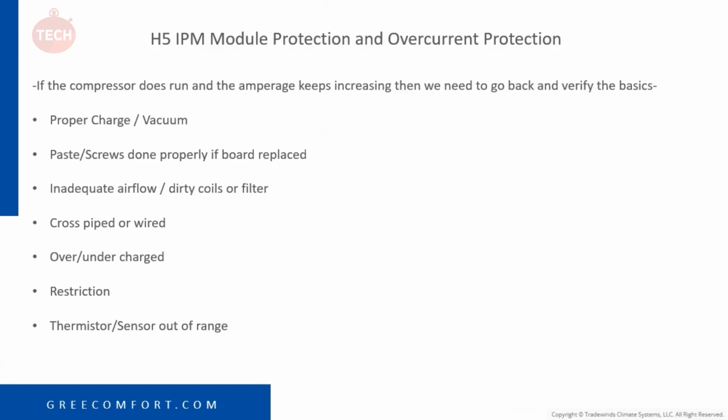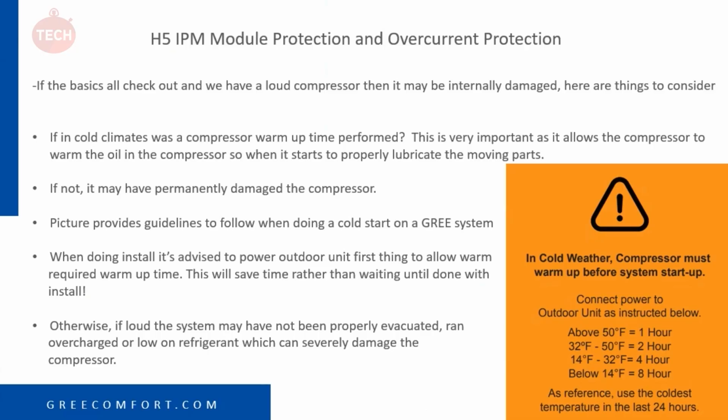Is the unit cross-piped or wired? Is the unit over or undercharged? Do we have a restriction? Or is one of the thermistors or sensors out of range? If the basics all check out and we have a loud compressor, then it may be internally damaged. Here are some things to consider.